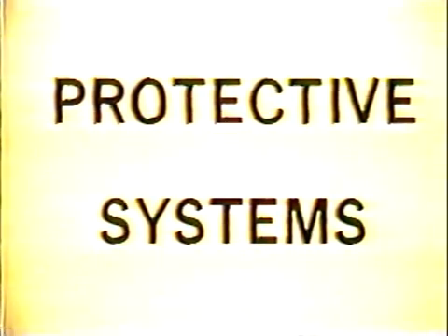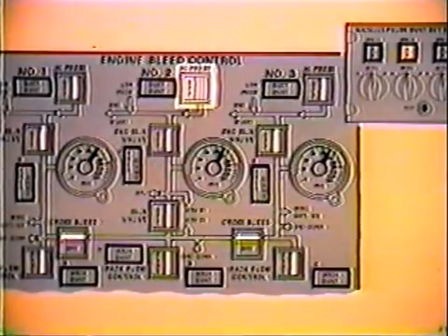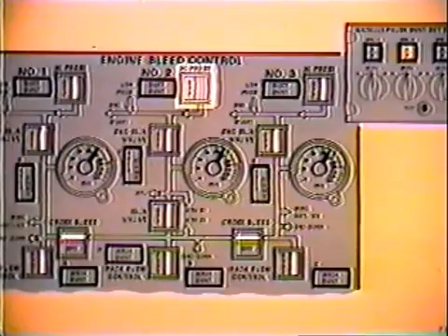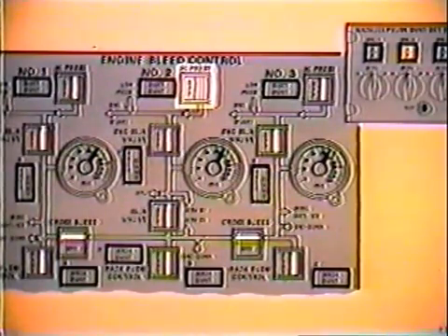The pneumatic system is provided with several protective functions. Some of these will provide indication only, while some others will take protective action. The nacelle pylon overheat detection system is designed to detect excessive temperature around the outside of the pneumatic ducting in the nacelle or pylon areas. The high temperature condition could be caused by a leaking high pressure pneumatic duct. This protective system will close and lock the high pressure valve for the appropriate engine.